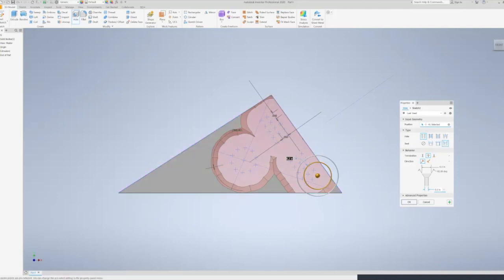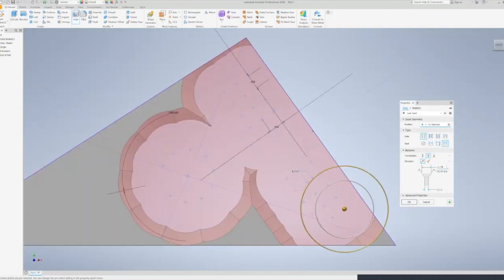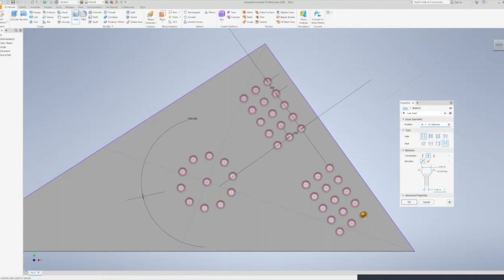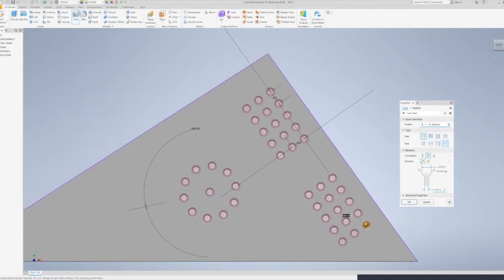And we could change all these dimensions. Let's make it something small for the purposes. You change it to like, I don't know, 0.03, 0.02. Yeah, that looks nice. Okay. And we could also change the termination. We could say to a specific surface, or we could just say, let's make this hole go through everything, which is what we're gonna do. And you could also flip it if it's necessary. And again, you can change all the dimensions of the holes. You can change the diameter of this part, you change the diameter of this part, and everything.